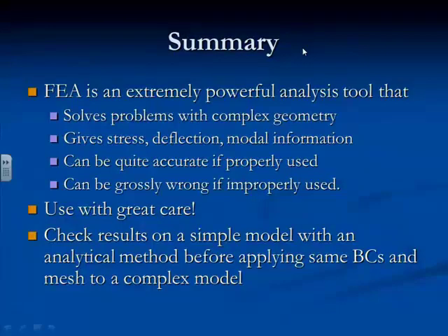You had a question. Yeah, like FEA will give you your principal stresses, so finding out if it will fail and anything with G loading is still done by hand? Yeah, pretty much. You take those numbers to a Goodman diagram, essentially. But now you've got presumably good numbers to take to the Goodman diagram, right? That's the big advantage of it. You've got good numbers if you were careful about the boundary conditions.